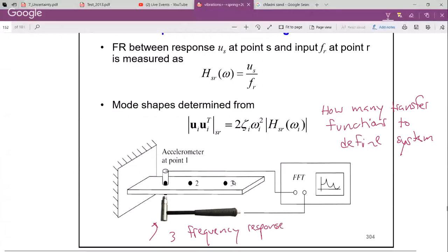Then, as I said, if you take our multi-degree-of-freedom equations of motion, which we used in the modal analysis procedure, right there in the frequency domain, we can get this relationship when we evaluate at the natural frequency. It basically gives us a relationship between the magnitudes of our motion and the magnitudes that we can extract from a frequency response measurement, and also damping ratio and frequency.